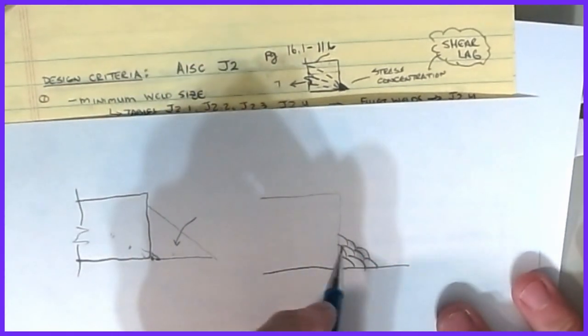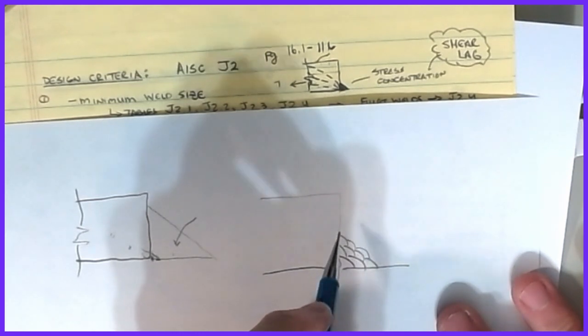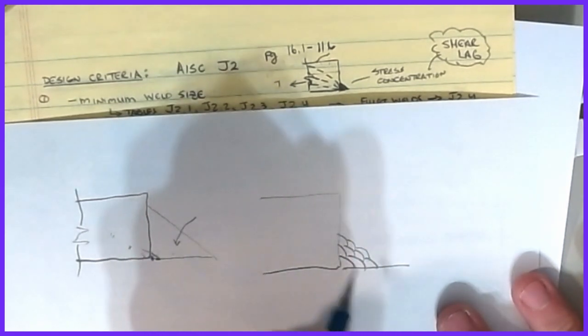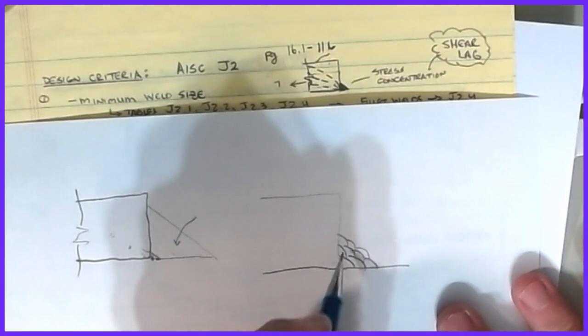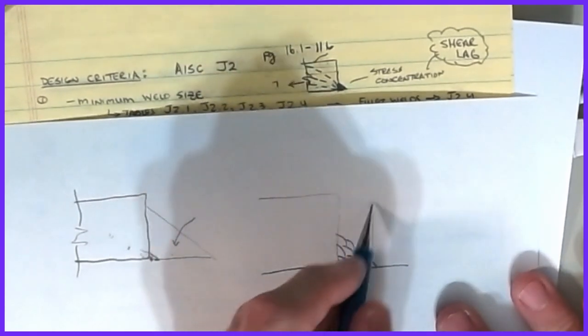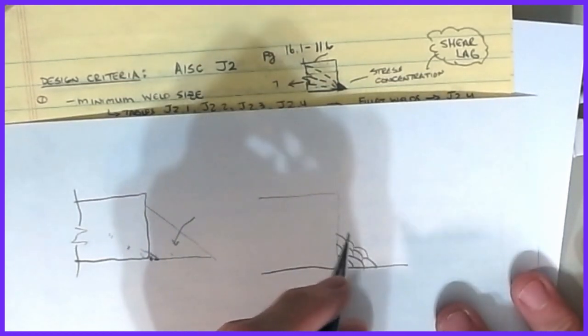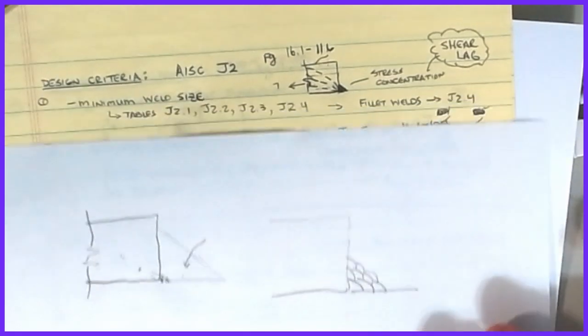But to get into these larger weld sizes, larger than an inch or an inch and a half of weld, not only do you have a major problem with heat, but I also have an issue with the time and the cost of doing these multiple passes, because the further I go out, the more passes it takes to build this thing up. Okay, all right. So that's always a consideration.